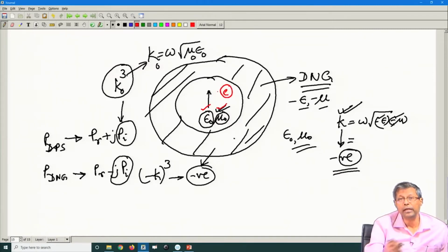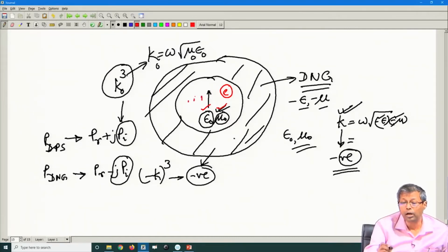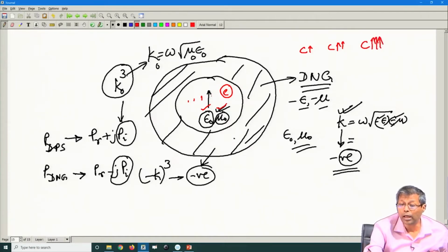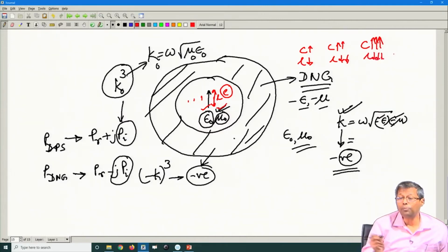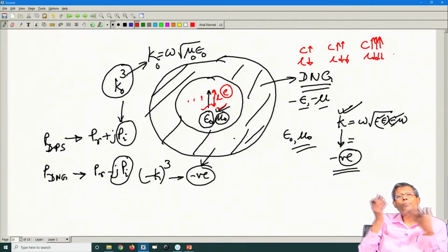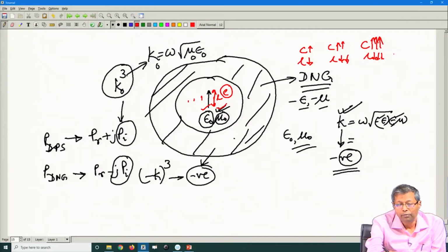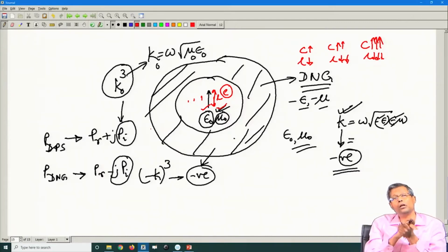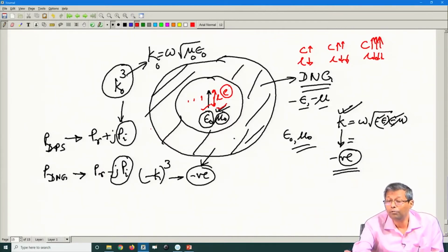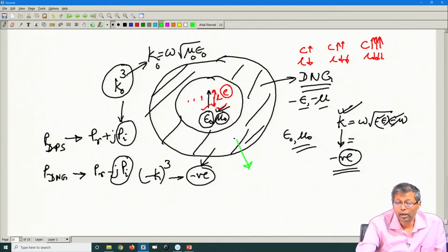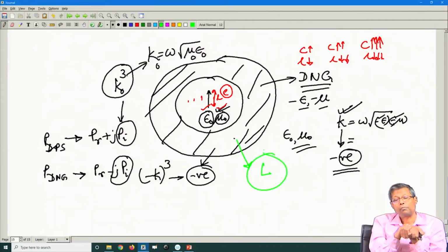That means, as you miniaturize this dipole, as you make this length smaller and smaller, it is seeing free space as a progressively higher and higher capacitance. In order to counteract this phenomenon, I cannot bring in a huge inductance to match beyond a particular level. So what I would do is surround it with a medium, which we call a double negative medium, that will give me an inductive load. This medium gives me an effective L.